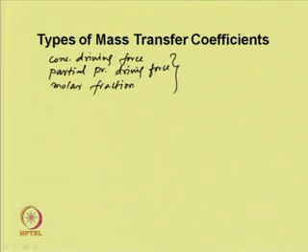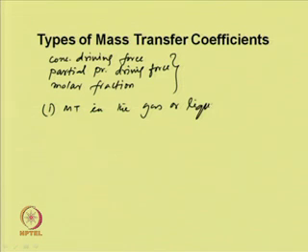So, on the following basis: mass transfer in the gas or liquid phase. If it is gas phase, there is a gas phase mass transfer coefficient. If it is in the liquid phase, it is a liquid phase mass transfer coefficient, and also the choice of driving force.